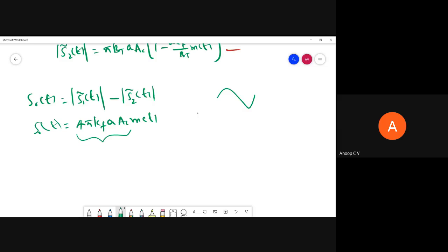So we have seen the block diagram now. We have a practical method of realizing this balanced frequency discriminator. So here we'll give S of t, that is the FM wave, to the input of a transformer, a center tap transformer.